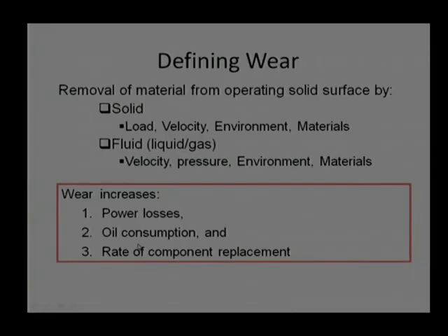Second is the oil consumption. If wear is more, then oil consumption will increase. There is a possibility of excessive leakage from the interface, and that will start consuming more and more lubricant, or we need to supply more and more lubricant. And finally, if there is more wear, there is naturally a possibility of replacing that component with a newer component.